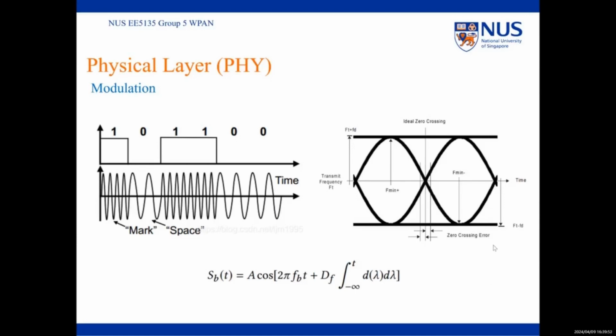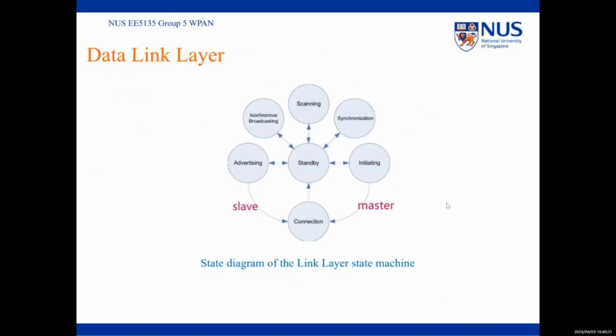Enhanced data rate compatibility is integrated into Bluetooth modulation as an additional feature, ensuring backward compatibility. While the Bluetooth modulation scheme and format aren't inherently suited for higher data rates, Bluetooth 3 doesn't alter the modulation format to achieve higher rates. Instead, it collaborates with IEEE 802.11g physical layers, enabling data rates of approximately 25 Mbps.